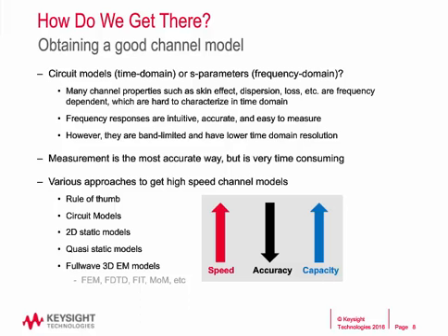since it accurately represents some key channel characteristics such as dispersion, crosstalk, skin effect, and others, which are frequency-dependent parameters by nature. However, they are band-limited data and also have a lower time domain resolution. Still, the measurement is the most accurate method, but it is a very time-consuming process.